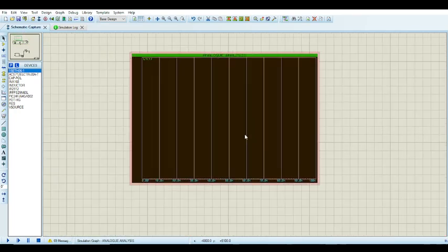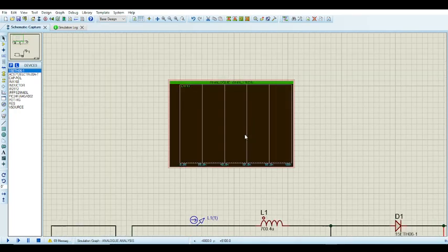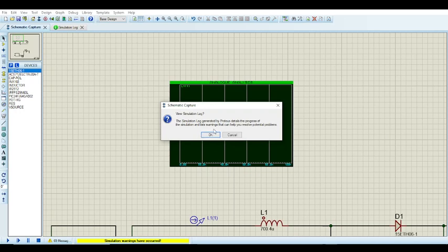All right. So let me just increase that. No, it's there, so I can just run it. Essentially, if you run the inner loop first, you can actually see what the issues are. Because if it's not settling to your set current, your IREF, then you shouldn't even bother to include the outer loop. You want to check the inner loop first and check that it's settling to the current that you need.